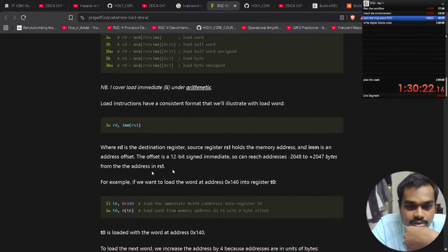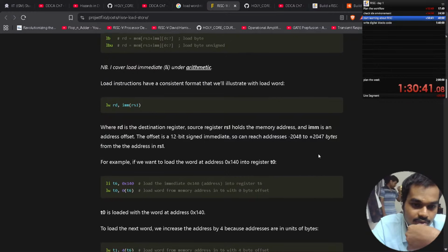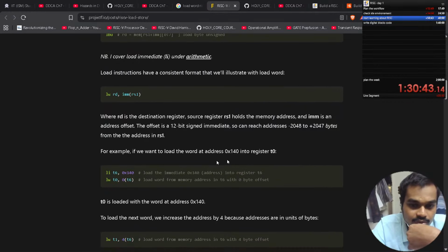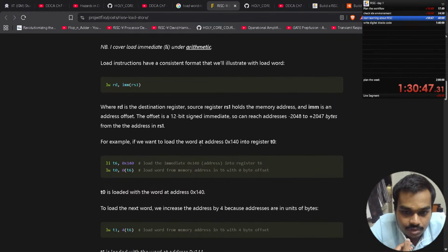The offset is 12 bits, so we can reach addresses around the address in RS1. So the offset can vary from -2048 to +2047. These are the values of offset you can take from the address which is in RS1. If you want to load the word at address 0x140...